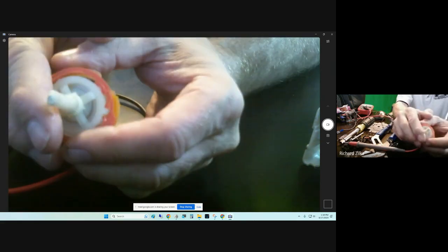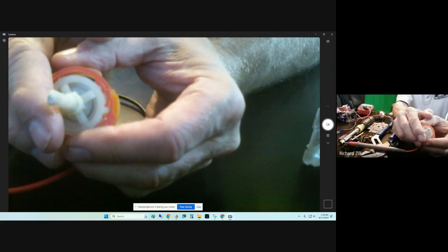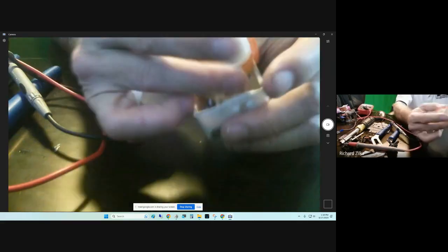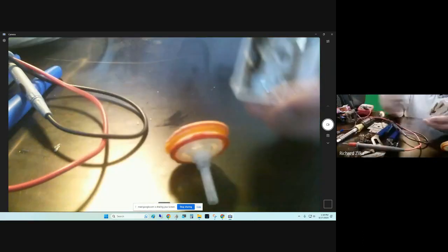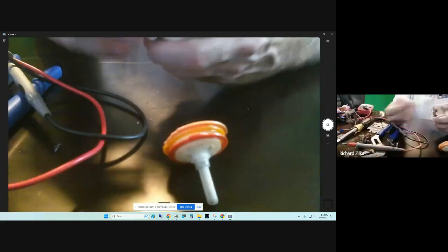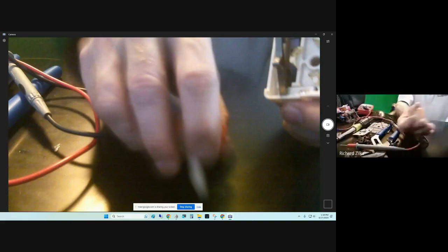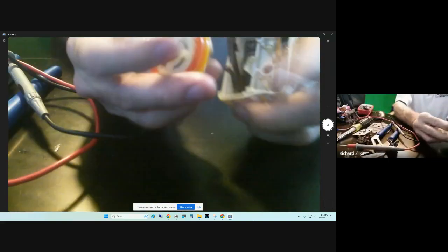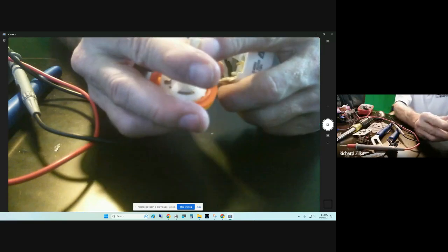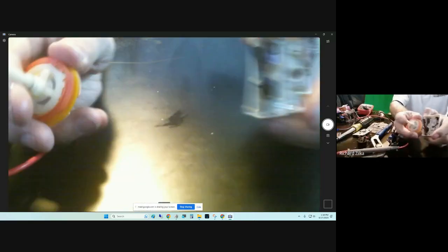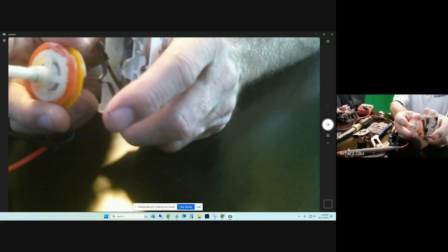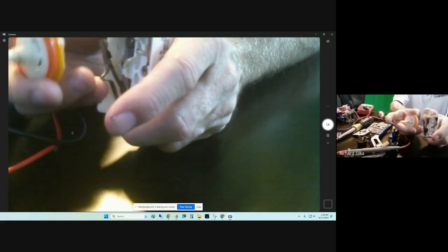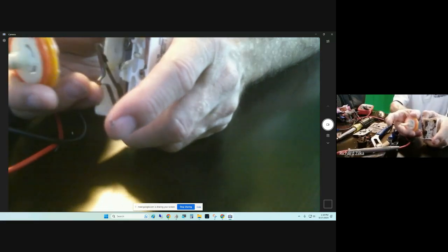You're like, man, I got this switch. I could just put this switch in, get this job and get out of here. Well, you saw I opened it up, right? I open these up all the time. And then I just put them back together with a pair of pliers, squeeze it back on. So why can't I take this cam out of the old switch and put the cam in the customer's new switch that has the right shaft and make it work? So I have switched cams out of switches to get a completed job instead of having to order the switch and come out.